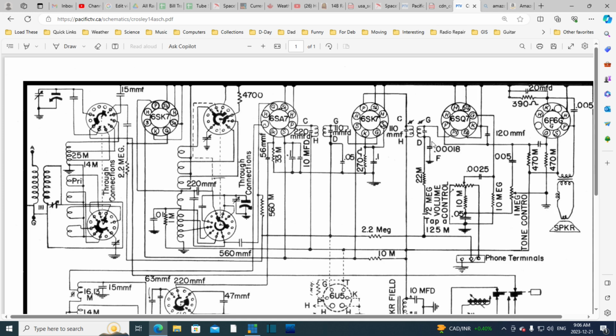So here we have the output of the radio part of the radio. Here it's a 455 RF signal, but it's detected or rectified by the diode, and at that point the audio signal is apparent. Prior to that, the audio signal is not very apparent. It's very hard to extract it.